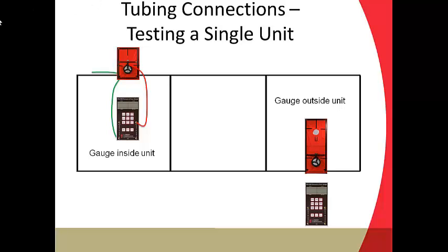When we have our gauge on the inside, remember what we're measuring is the house with respect to outside, right? House to outside. We're used to just running the green tube to the outside and not worrying about the input, but the input becomes more important and you have to think a little bit more about what you're measuring. On channel B, we're measuring the pressure at the flow sensor of the fan.